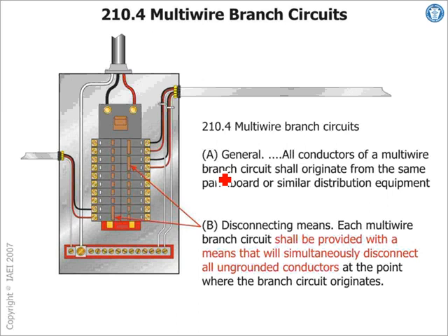Branch circuits only if they are in the same gutter or the same box or the same conduit. So if they're not in the same box, gutter, or conduit, so like this panel is 480, all the 480 conduits are separate from 208, then you don't have to identify the branch circuits. What they don't want you guys to do is open a box and see two whites. Which one of them goes with 208 and which one of them goes with 277? Would you be confused? Anyone can be confused. Now you open a box and you see one gray and one white. It's very clear.